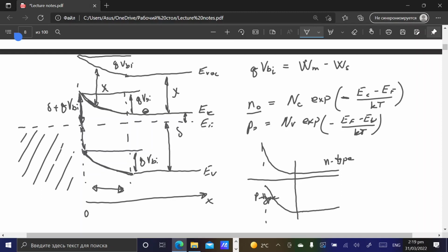That means forward bias: we reduce the potential barrier and make the depletion layer thickness smaller. Or there is the possibility of reverse bias. When the external electric field adds to the internal electric field, we increase the thickness of the depletion layer and we increase the resistance of this junction, because the depletion layer becomes thicker and contributes more towards the total resistance of this junction.